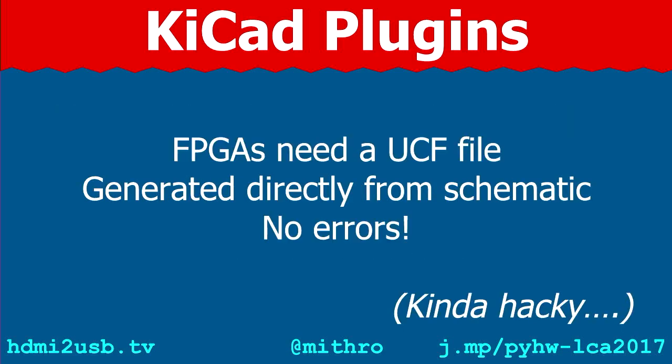FPGAs, because they're configurable, let you connect anything to any of the pins, but on a circuit board, your pins are hardwired to certain peripherals. And so you need a file that tells you what the FPGA is connected to. So I have a Python script that takes the schematic and generates that description. It means that we're not going to have a translation error from converting from the schematic to the UCF description, because it's done automatically.